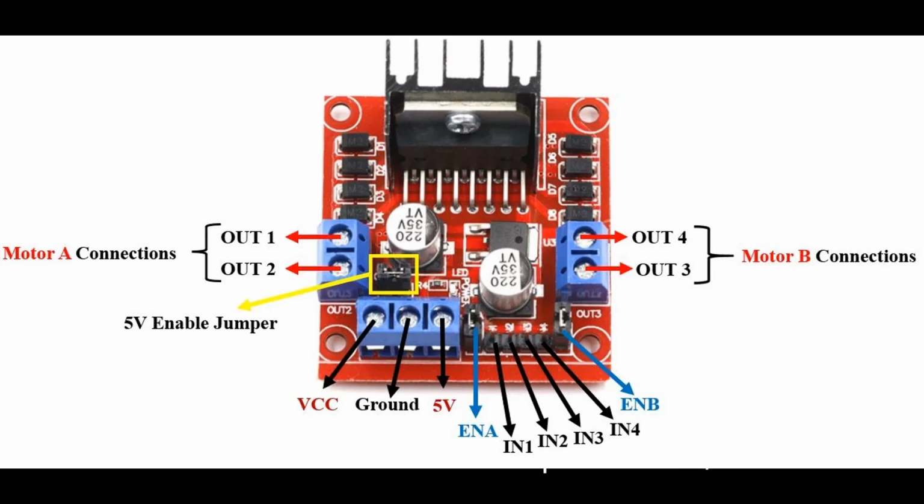C. Direct Torque Control, DTC. Function. DTC is a more advanced control method compared to vector control. It directly controls the motor's torque and flux without requiring the intermediate step of current regulation. Operation. DTC uses real-time feedback from the motor to adjust the torque and flux. This results in faster torque response and more accurate motor control. DTC is typically more sophisticated and provides a smoother, more responsive performance.